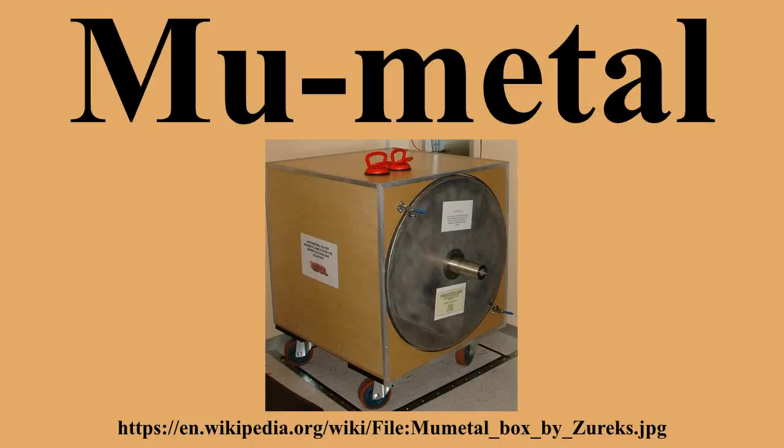Mu metal is a nickel-iron soft magnetic alloy with very high permeability suitable for shielding sensitive electronic equipment against static or low-frequency magnetic fields. It has several compositions. One such composition is approximately 77% nickel, 16% iron, 5% copper and 2% chromium or molybdenum.